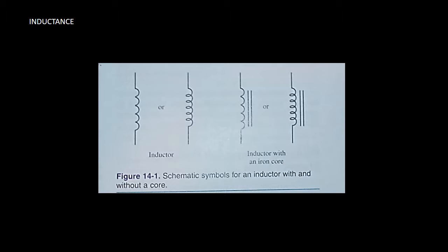Set up the experiment from Chapter 10, Figure 10-2, using the hollow coil connected to a galvanometer. Move the permanent magnet in and out of the coil and notice the deflection of the needle in the meter. When the magnet moves in, current flows in one direction. The current reverses direction when the magnet is withdrawn. No current flows unless the magnet is moved.